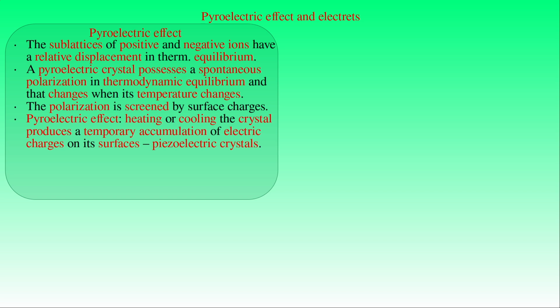All pyroelectric crystals are piezoelectric because every polar crystal lacks inversion symmetry. However, the converse is not true. Most piezoelectric crystals are not pyroelectric because they do not possess a spontaneous polarization. Examples of pyroelectric materials include tourmaline, lithium tantalate, and many ferroelectric crystals such as barium titanate below its Curie temperature.